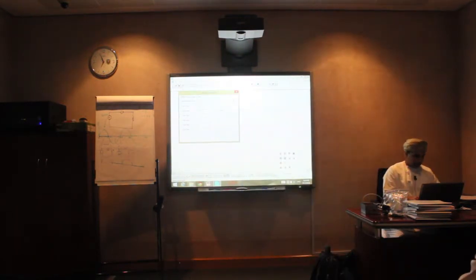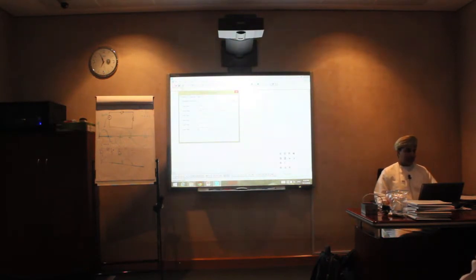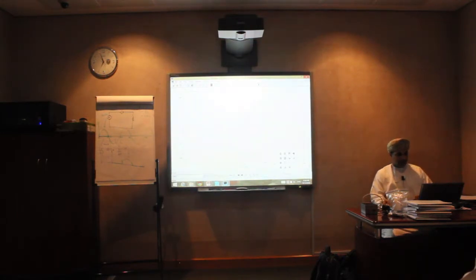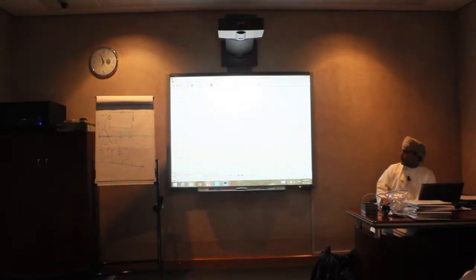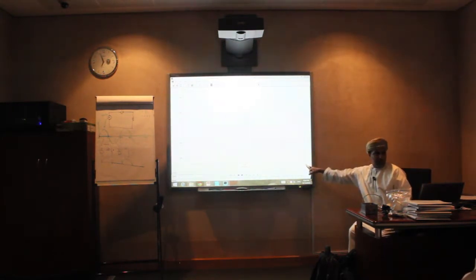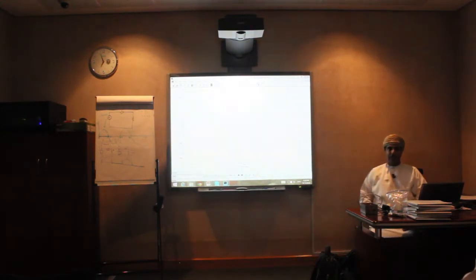So the total time is 0.04 seconds, and the step, which is the increment, means start to simulate incrementally, incrementing by 1 times 10 to the minus 5. Then close that one in order to select it. So now if we run that, we can see the source. See, this is our source. The source is sinusoidal, 40 milliseconds, which is 0.04 seconds, right? So this is our input.